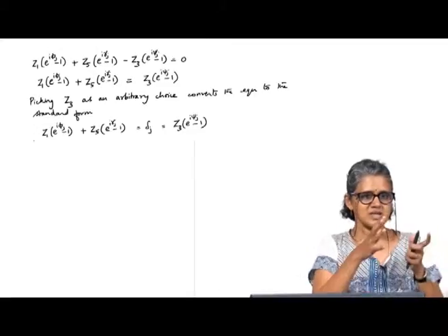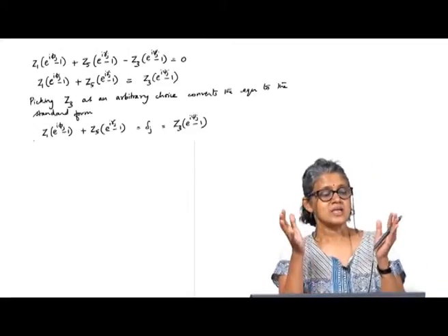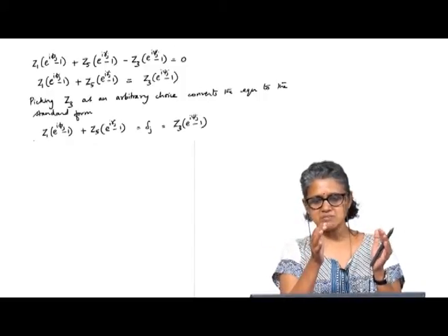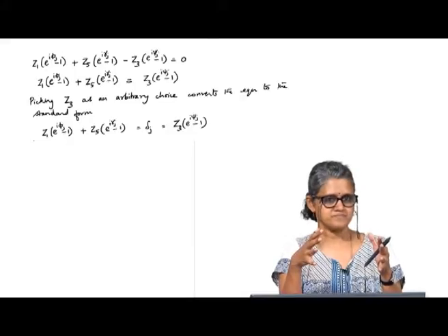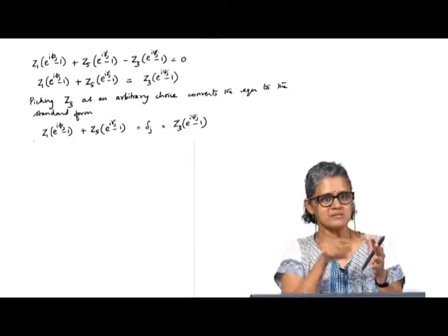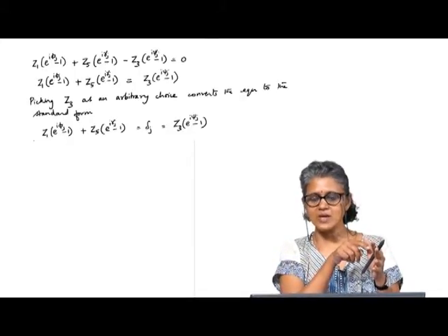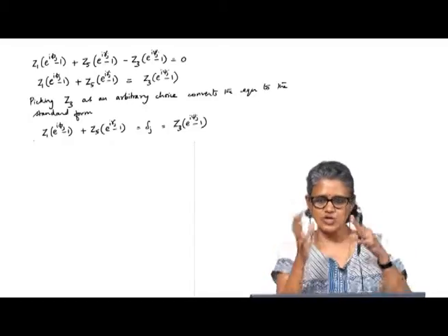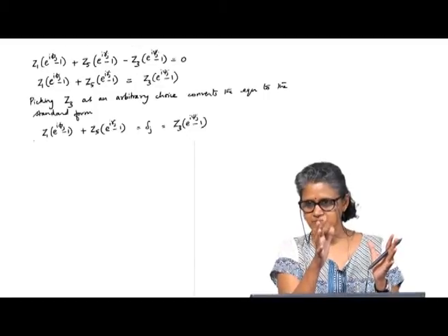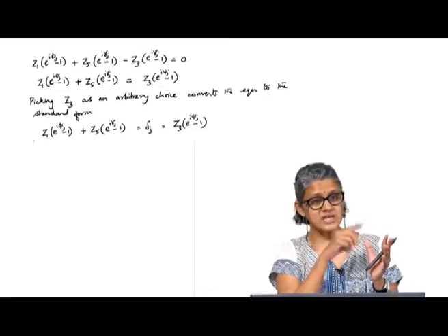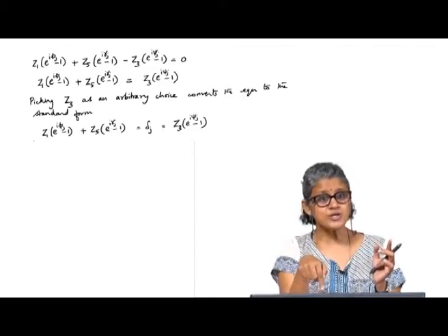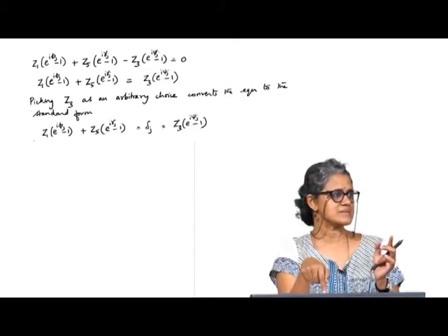Remember, in function generation, the input and output are internal to the system, internal to the kinematic chain. So, we have seen earlier that scaling it or changing its orientation will not change the input output relationship. That is what you are doing when you pick z3.